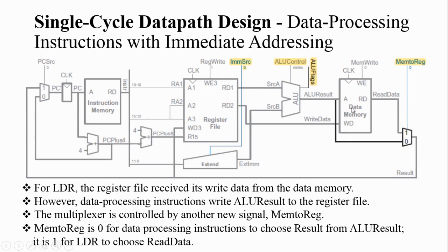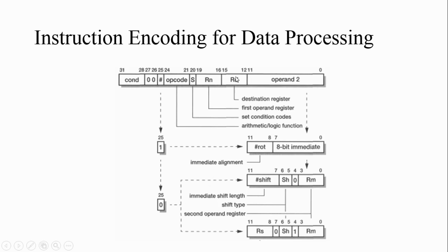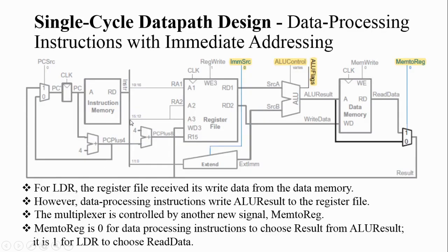So for storing that, you are storing it in the register. So how will you do that? The ALU result will be holding the processed value. That processed value you need to store into whichever register it is. Right? So how will you configure the register? Bit number 12 to 15 is used for configuring the destination value, so that it is already connected.